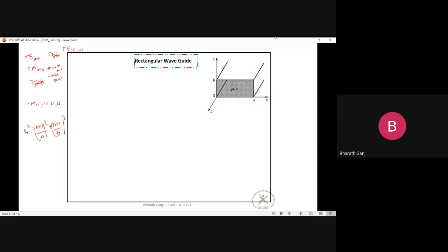And one thing which I ask you to remember is the field components for the TE10 mode. For TE10 mode, you have an Ey component which varies like sine of pi x by a, which is a half sinusoidal variation along the x-axis, with this being a and this being 0. So this is your rectangular waveguide, and your magnetic field will have z and x components. These are the things which you need to understand and remember about the waveguides.